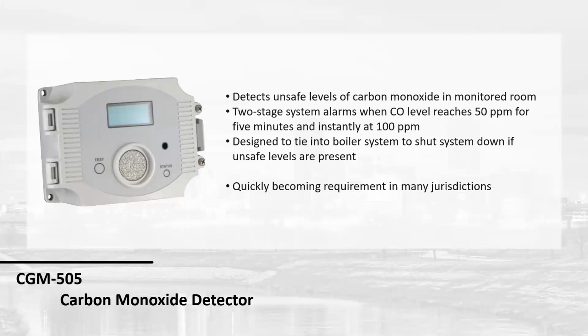It does not go through a BMS, does not go through some secondary thing, because that is something that can be bypassed with a simple jumper. We recommend tying this in again directly to the auxiliary limit circuits of the appliances. If you're doing a draft control system, we're going to tie this into our draft controls, because our interlock controller is tied into the auxiliary limit system. So by proxy, we are tied directly to the auxiliary limits.